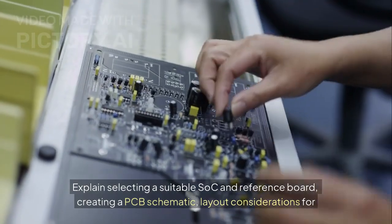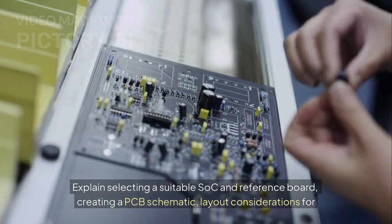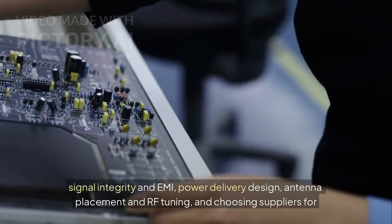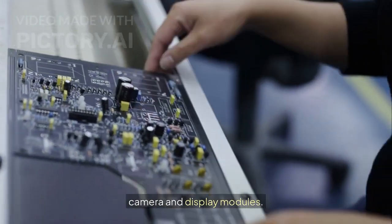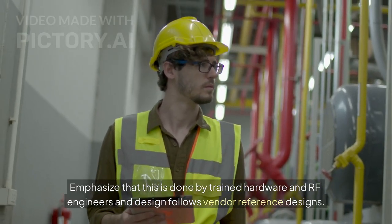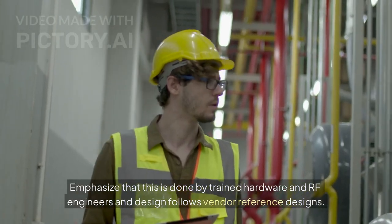Explain selecting a suitable SoC and reference board, creating a PCB schematic, layout considerations for signal integrity and EMI, power delivery design, antenna placement and RF tuning, and choosing suppliers for camera and display modules. Emphasize that this is done by trained hardware and RF engineers and design follows vendor reference designs.